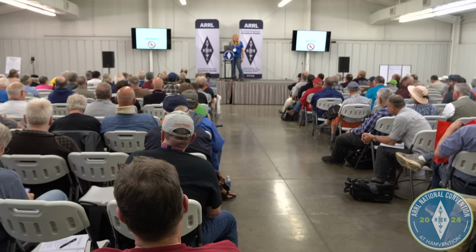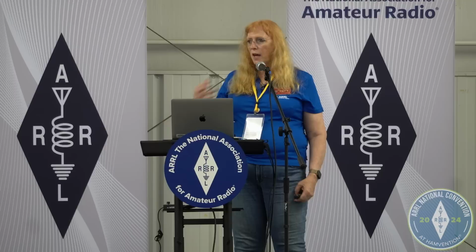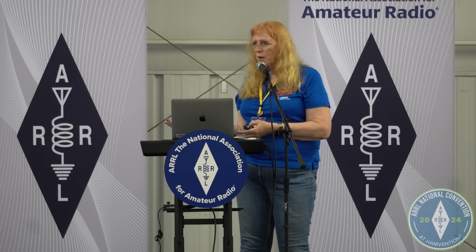So, that's it. I mean, if you want to feed like a dipole, and the dipole has balanced line coming down, then a one-to-one balun will decouple the voltages so that you don't have this imbalance where, you know, the chassis of the radio is connected to part of the antenna system, which may not be what you want.